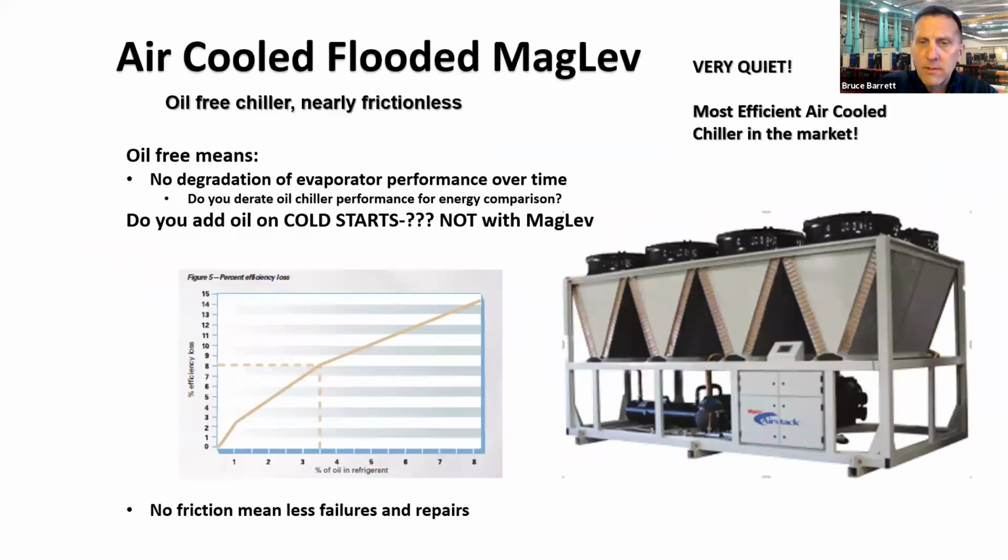Air cooled, again, applies. When your air temperature is cold and dormant, refrigerant is going to find its way to the condenser coil. You can't have a cold start. You've got to continue to refill the oil reservoir to get that compressor properly lubricated. These compressors are extremely quiet. We do put them in our air-cooled machines in an insulated box to keep them warm and toasty with the heater, so the computer components don't get too cold. But again, it's still an impact of oil on performance in air-cooled machines.